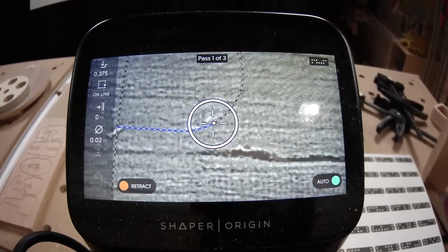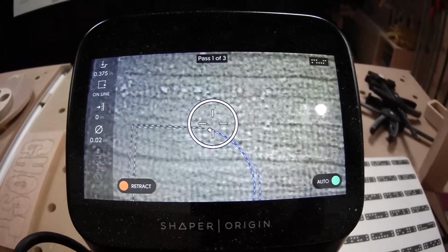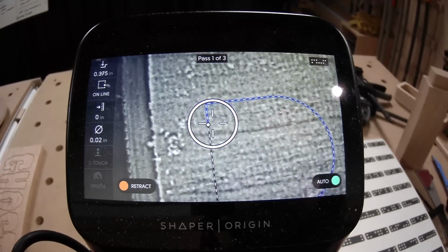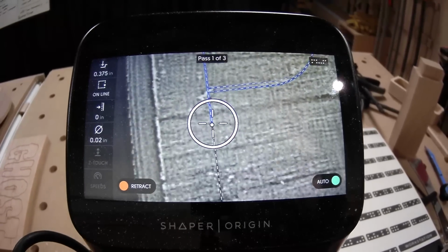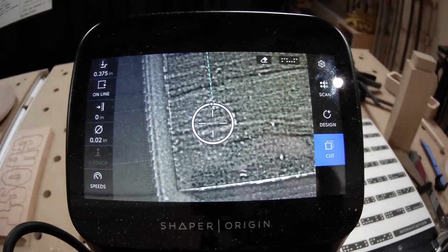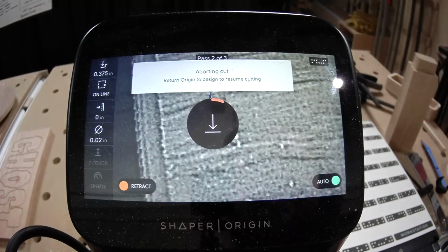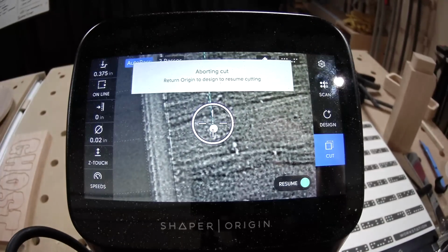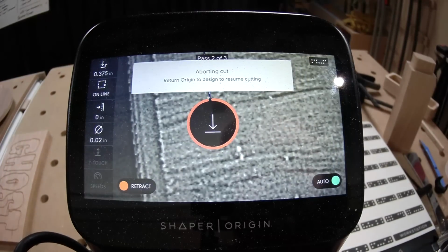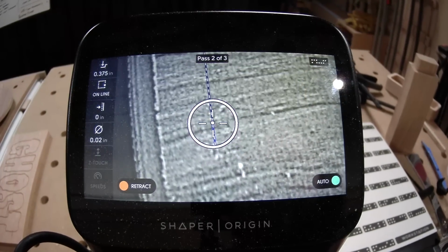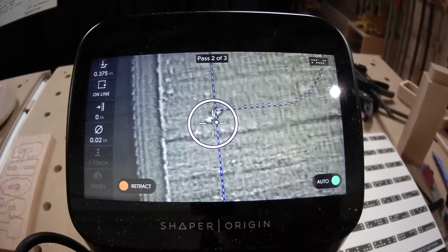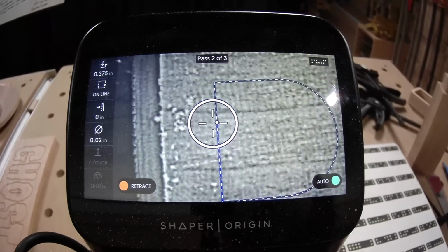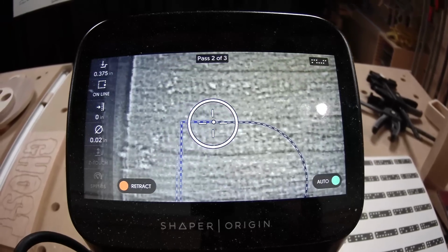Now here's something that's really important about these engraving bits. The deeper you go, the wider that cut gets. So as you're stepping that cut down, the same increment for every cut, it's getting heavier and heavier. You're not just removing more depth, but you're also removing more width every time. And you can see there where Jake went a little too fast before it finished plunging. So when you get to those ends, you'll just have to give it a minute.